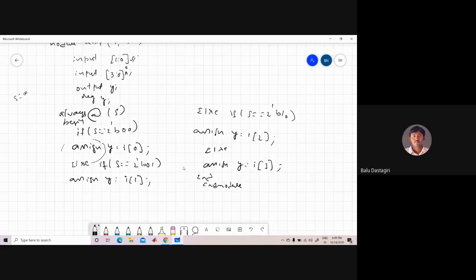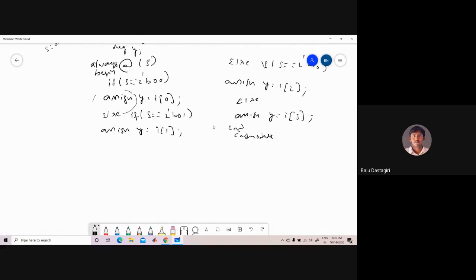Now, in the previous case we used the D flip-flop. Now let us write the D flip-flop by using the assignment statement. D is the input for the D flip-flop, and we have the clock, for which you can use the negative edge. You have the clear, the preset, and the output Q and Q bar, where Q and Q bar are opposite to each other.